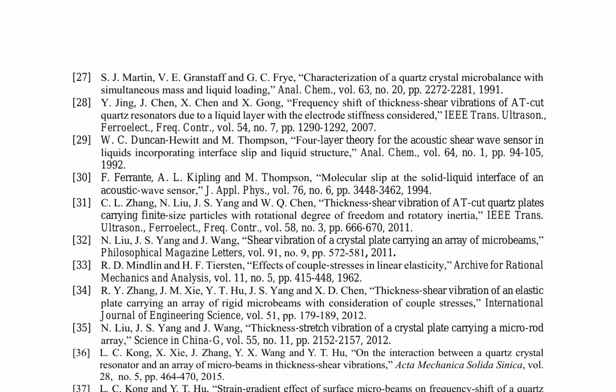Quartz crystal microbalances, widely employed in sensing applications, exhibit complex frequency responses influenced by mass and liquid loading. A thorough examination of existing research reveals that the quartz crystal's resonance frequency decreases with increasing mass loading, a phenomenon attributed to the added mass and stiffness of the deposited material. Conversely, liquid loading induces a dual frequency response, with the higher frequency corresponding to the quartz crystal's resonance and the lower frequency resulting from the liquid's viscoelastic properties.